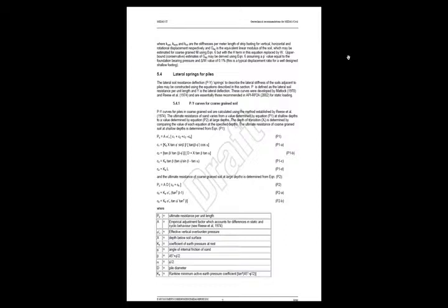There is a question by Christian. The question is, what about the live loads? How does Midas consider masses for response spectrum? Well, the live loads generally, you can take into account 20% of the live load or 30% of the live load, depending on what the code says. And it's very easy. You just have to apply additional load in the Midas software or any other software. Just define additional mass based on the live load, and then you can perform response spectrum analysis.